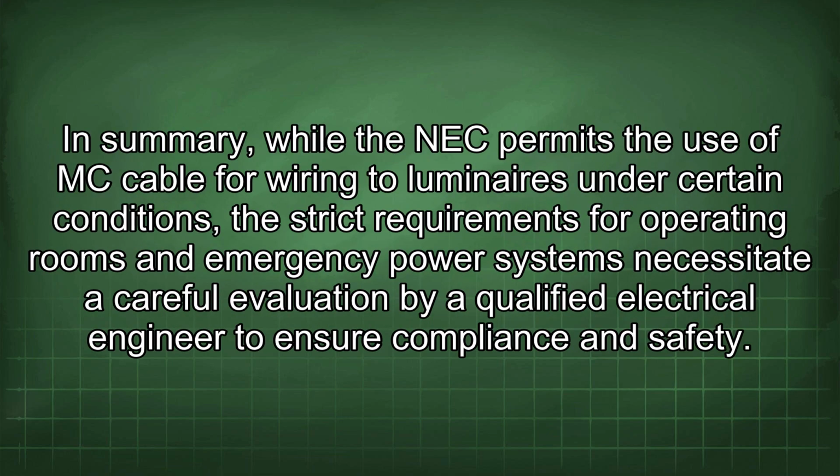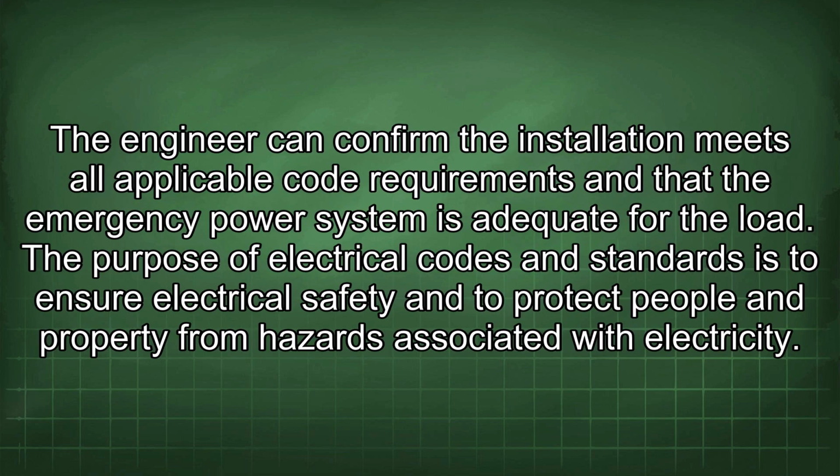In summary, while the NEC permits the use of MC cable for wiring to luminaires under certain conditions, the strict requirements for operating rooms and emergency power systems necessitate a careful evaluation by a qualified electrical engineer to ensure compliance and safety. The engineer can confirm the installation meets all applicable code requirements and that the emergency power system is adequate for the load. The purpose of electrical codes and standards is to ensure electrical safety and to protect people and property from hazards associated with electricity.